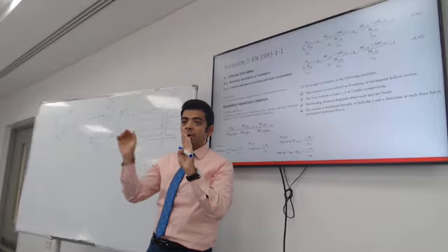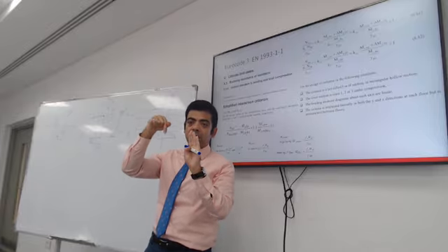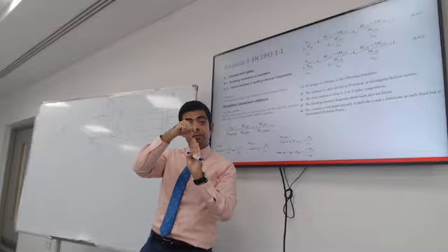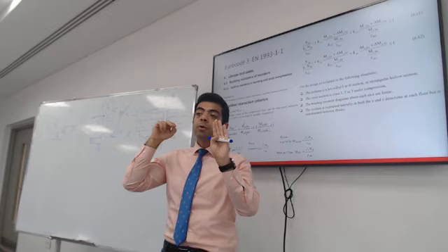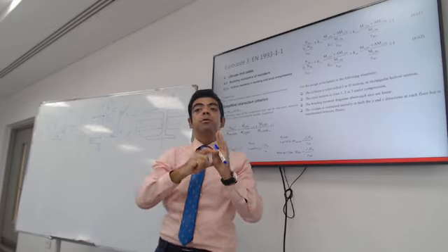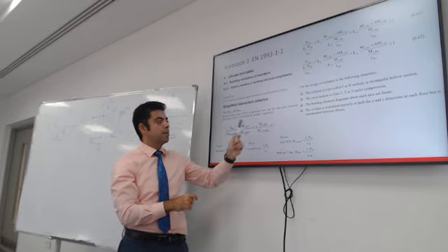Remember what we talked about? The reaction of the column is not applied at the center line of the column. The reaction of the beam is not applied at the center line of the column. So this distance will introduce the moment about y and about z.